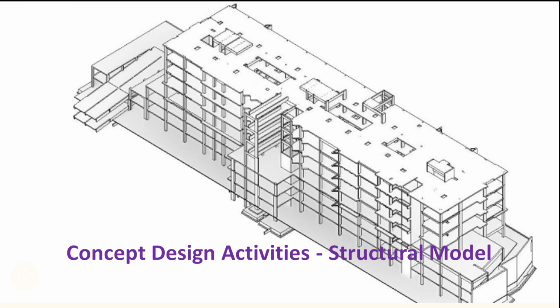Concept design activities: structural model. Activities that form the framework: schematic representation of existing model as a background starting point; schematic layout of major process structural elements represented at LOD 100 or 200, like walls, floor slabs, columns and column grids, and so on; approximate layout dimensions, element sizes, and orientations.